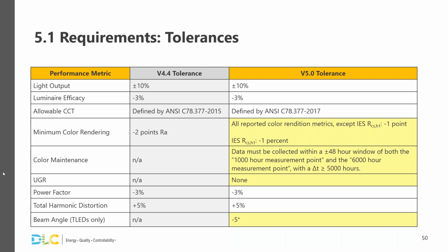So rather than having an effective UGR criterion value, including the tolerance, of 26, we essentially were more lenient and made it 27.9 to account for testing differences in the IES file, but the same meaning is there. So as long as you are at 27.9 or lower for high bay, you comply. The same for troffers or linear ambient. As long as you are 21.9 or less, you again are in the same step range as 19 up to 22.